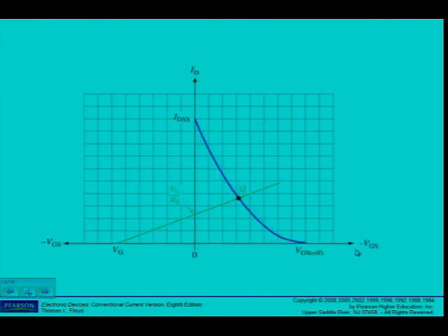Anyway, I made an example again because I told you I'm very good with Photoshop. So I swapped it around. Of course, for the P channel, it would look this way, right? So make sure VGS off for a P channel now is positive. So my characteristic curve will lie on the right-hand side of the ID axis. Okay.